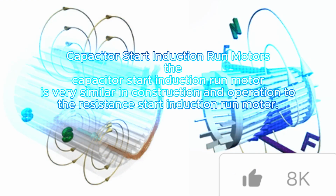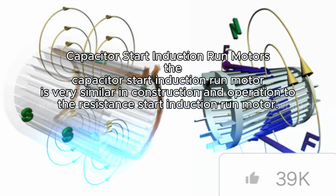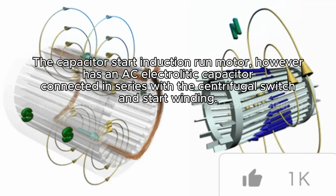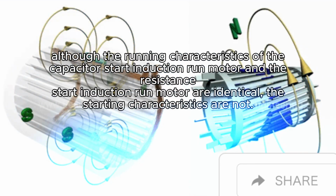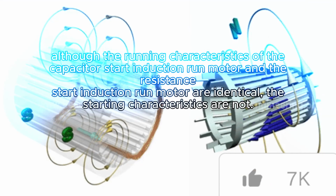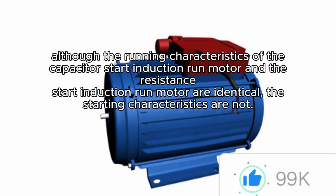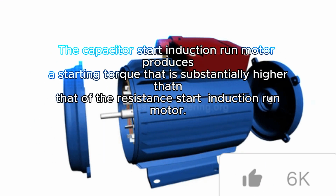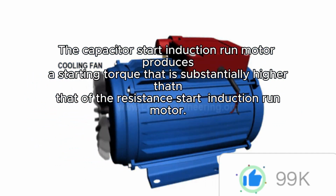Capacitor start induction run motors. The capacitor start induction run motor is very similar in construction and operation to the resistance start induction run motor. The capacitor start induction run motor, however, has an AC electrolytic capacitor connected in series with the centrifugal switch and start winding. Although the running characteristics of the capacitor start induction run motor and the resistance start induction run motor are identical, the starting characteristics are not. The capacitor start induction run motor produces a starting torque that is substantially higher than that of the resistance start induction run motor.